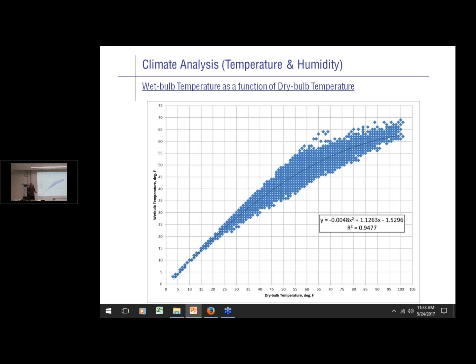If you haven't used scatter plots, then you probably haven't used the trend line feature built into the scatter plots. This is a graphical regression feature built into Excel. So you can curve fit a number of different curve forms and show the equation of that curve as an output on your graph. And now all of a sudden you've got a nice little regression equation that you can plug into a simpler calculation to do pretty sophisticated stuff. And it all starts deriving from extracting the hourly data and processing it.